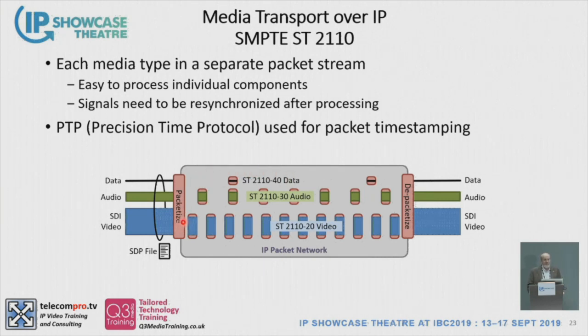The challenge, of course, is I've got to do two things. One, I've got to maintain synchronization from my input to my output, and that's the job of Precision Time Protocol, which Ed will go into in a lot more detail. And two, the Session Description Protocol file. This is a text file that describes how each one of these packet streams is formatted, and it can also talk about the relationships between the different packet streams.